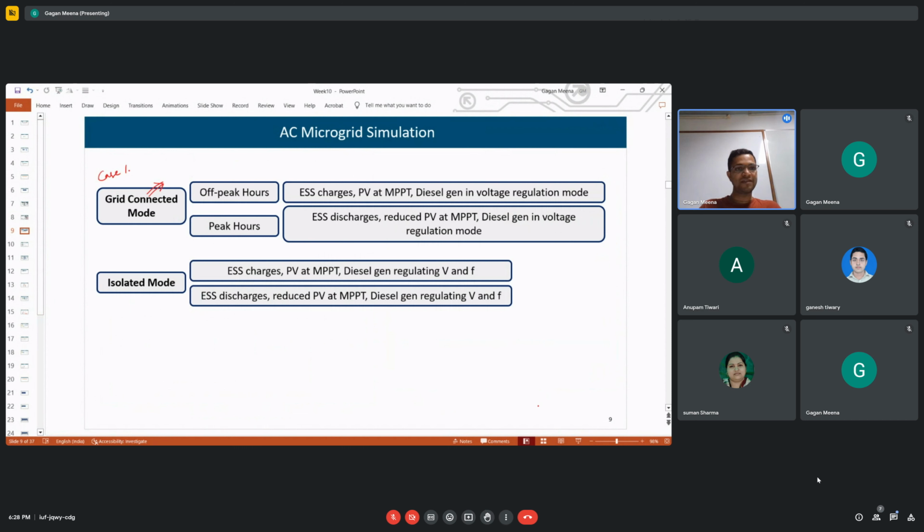So if the storage SOC is less than 40%, then we have to check the diesel generator. And what do we have to check? We have to check whether the output of the DG, P_DG, is greater than P_load minus P_generation, that is, load minus solar plus wind generation.